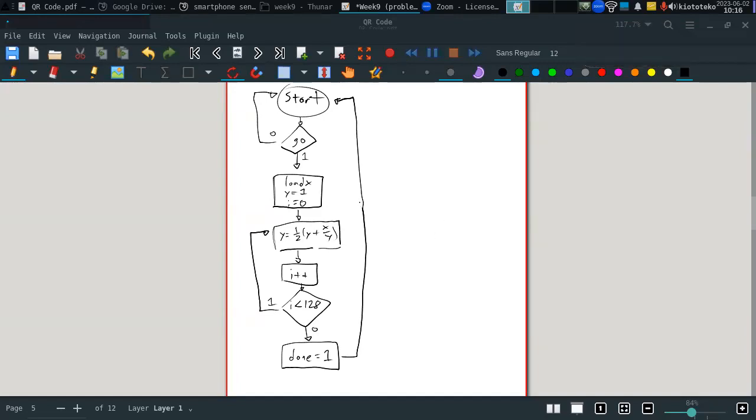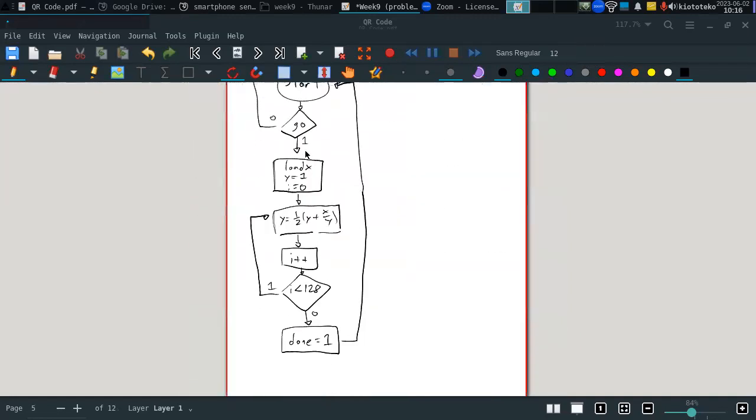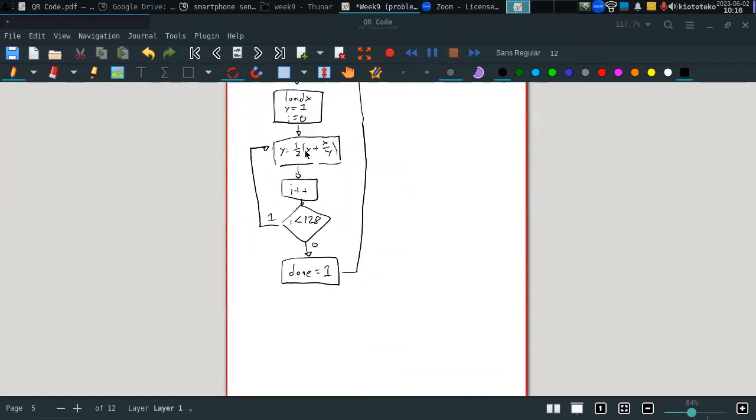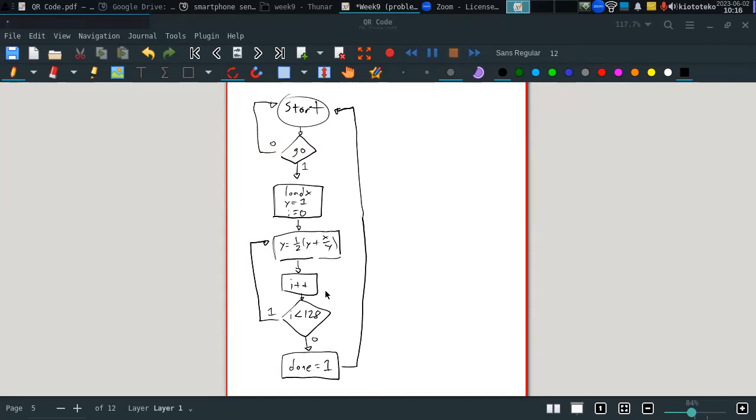Does done equal 1 represent actually setting the variable done to 1? Like why does it go over 1? Oh, because go depends on the user, but done is something that is activated by the circuit itself. Yeah, well, in here we're assuming that done is equal to 0 everywhere except here. There are some limitations in the way you can express things in here, but we can just say that it's like this.